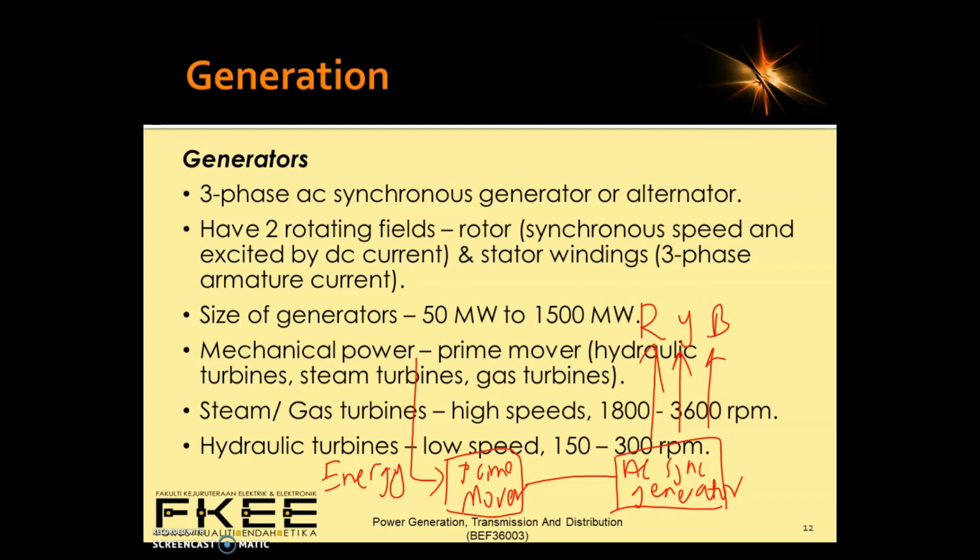The arrangement essentially employs, as you can see in this figure, an AC synchronous generator. We couple it with a prime mover. The prime mover is driven by the energy obtained from various sources such as burning of fuel, pressure of water, force of wind, and etc. You can see here, for example, we have the energy from sources of chemical energy of a fuel, for example, coal.